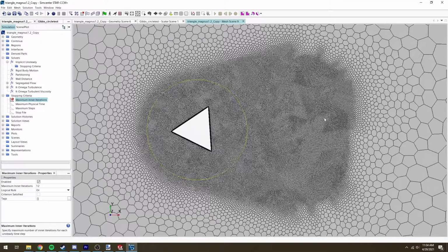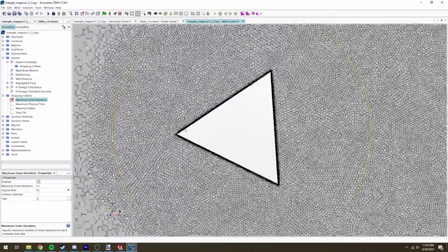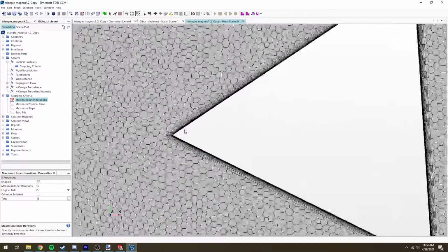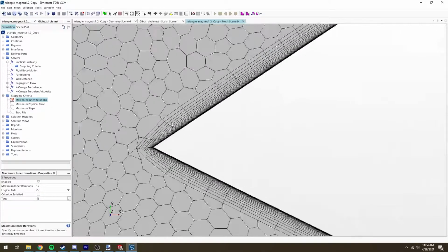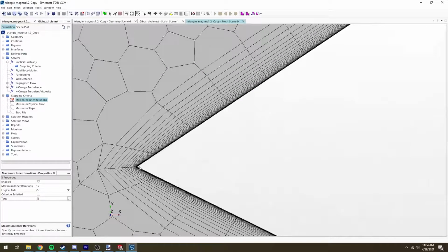We also had a wake refinement behind the geometry of the plug, in the X direction with a 15-degree spread, 100% base size, and a 1.3 growth rate. We also applied a 2D mesh to the plug field, with the same base size and the same growth rate. We also had a uniform control to make each element similar in area. And we had 25 prism layers at the walls of each polygon, with a stretch factor of 1.2.